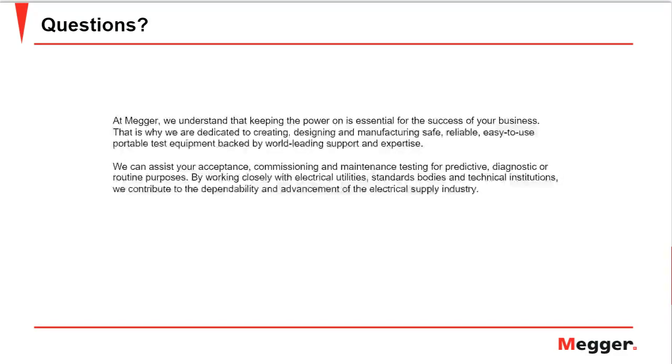At the end of the day, your goal is to make sure the negative sequence curve lies in between the downstream phase overcurrent curve and the upstream phase overcurrent curve. That's the end goal, so that you can protect your system and have negative sequence being more sensitive than the upstream element. I hope I answered that well.